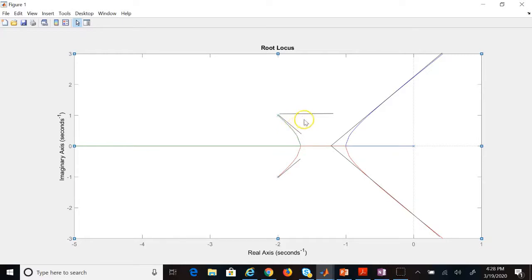And clearly you see, because this angle from horizontal to this is clockwise, it is negative 63 degrees. Similarly, if I calculate it for P3, it's going to be the opposite of that, positive 63 degrees, right? So the angle of departure from this is negative 63, from this one is what? Positive 63.